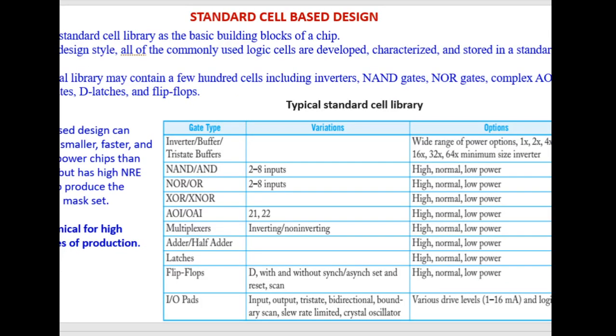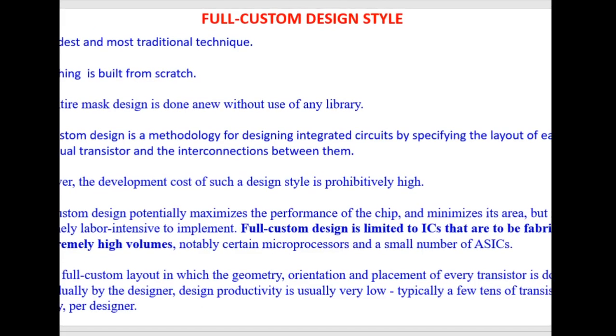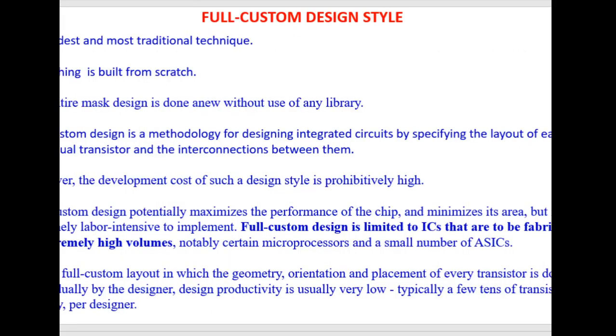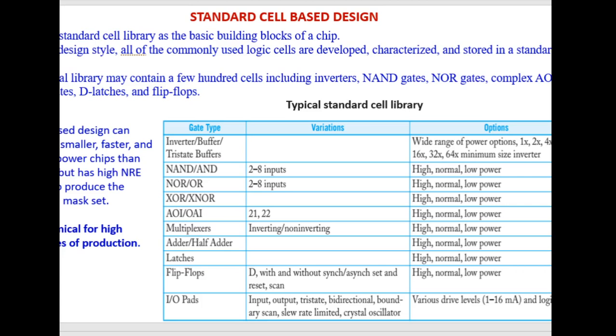So next comes the standard cell based design. It will come under the semi-custom VLSI design style category. This standard cell based design is also simply called cell based design style, but the term standard cell based design is more popular. What separates it from the full custom design style is that there is an availability of a library in this case.